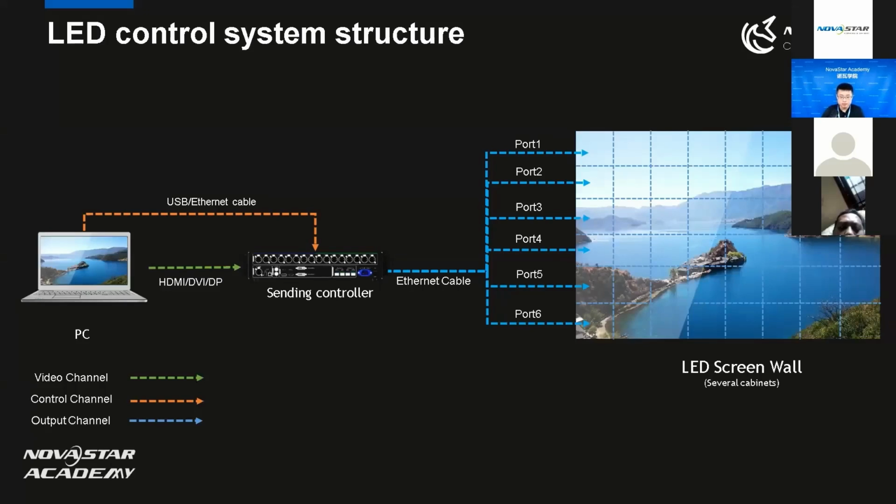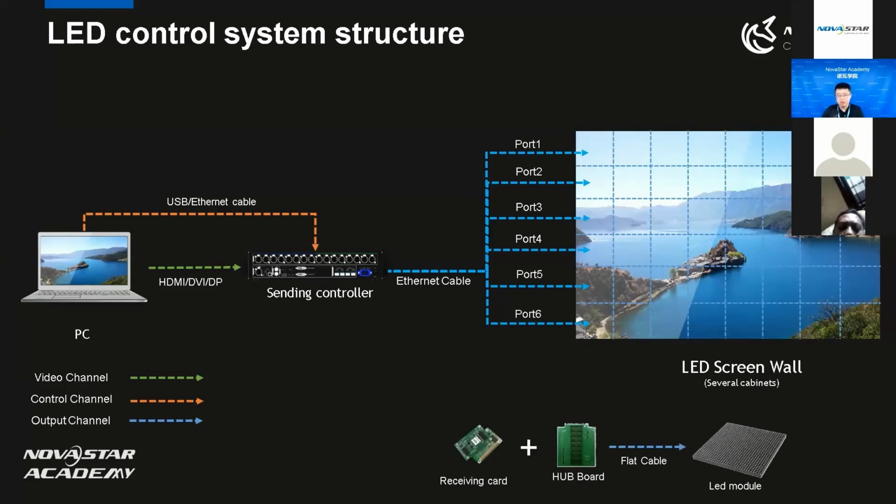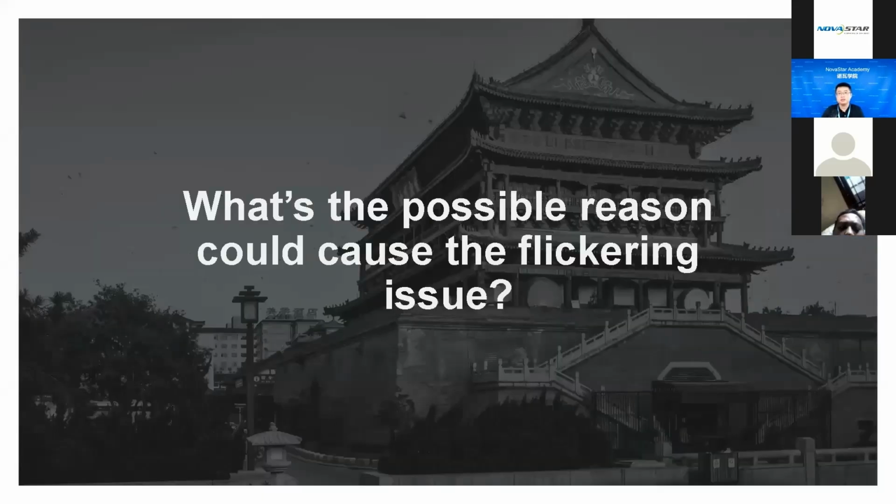For this question, we still need to do troubleshooting step by step. And all the factors, all the devices here could be the possible reason. It's same as screen blackout. We have PC, sending card, receiving card, LED screen, hardware receiving card, and flat cable, LED module. So all these factors could be the reason.